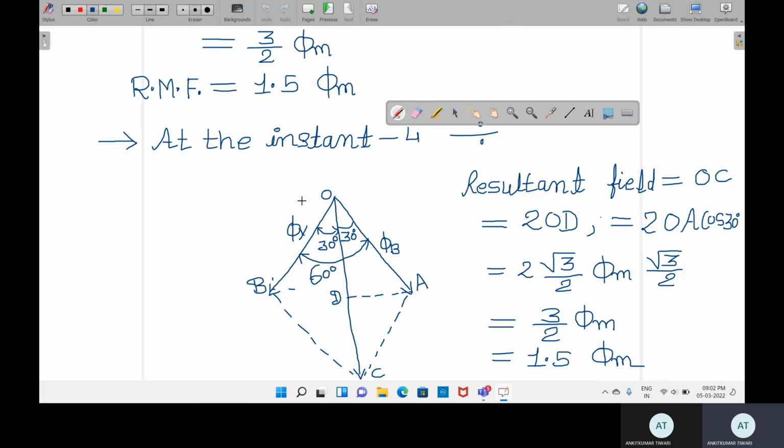It will not be a stationary magnetic field. So this has been learned by us. Whenever we give three-phase supply to the three-phase system, it will produce three fluxes, and all these fluxes will produce the magnetic field in rotation mode, so these are called the rotating magnetic field produced by the three-phase system.